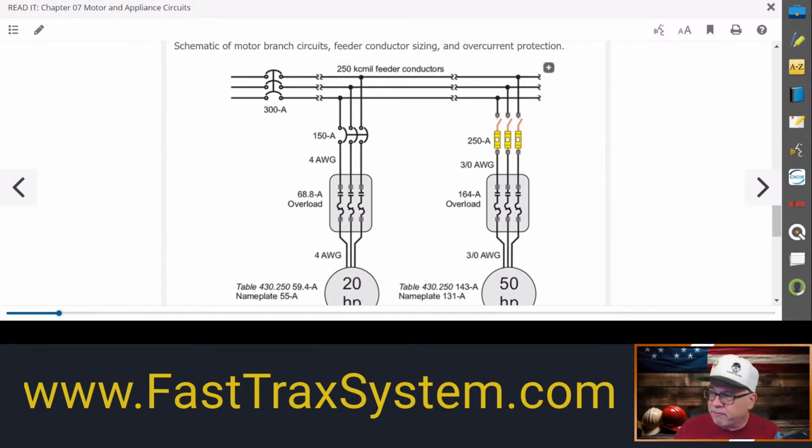So when we're talking about fuses, all we have to do, and in our lesson, it tells you the type of fuse. So you don't have to worry about that. We always want to tell you whether it's just a regular, simple fuse, one blow, one and done, delayed, whatever, always given in our examples. For you, it's going to be very much dependent on what type of fuse you're dealing with, right? So in our case here, let's go on and look at 430.52 again, because we're doing short circuit ground fault protection. So let me get to it here.